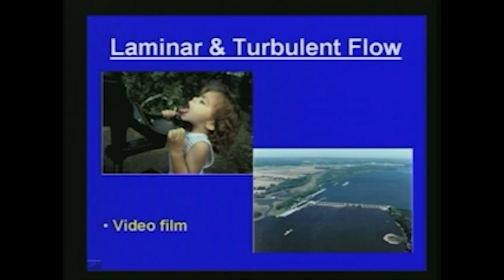In this photograph you can see that whenever the valve is opened very slowly, the flow comes out in layers, or laminar type, and when you are opening more, when the discharge is more, when the velocity is more, a lot of disturbance and mixing takes place and the flow becomes turbulent. So, again we will see how the flow can be laminar or turbulent in an experiment which we conducted in our hydraulics lab.